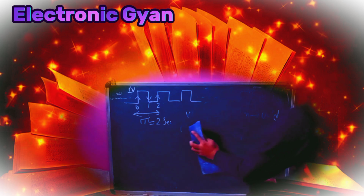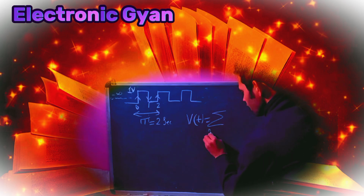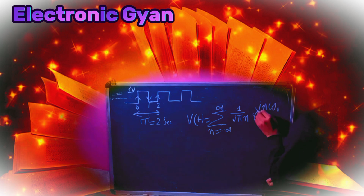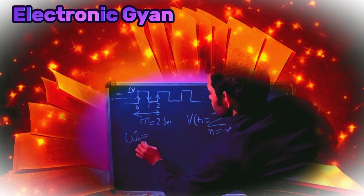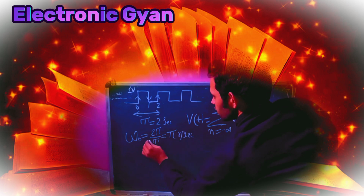Now we are going to find the Fourier series expression for the square wave pulse. That is nothing but v of t equal to summation n equal to minus infinity to plus infinity of Cn, where Cn is 1 by j pi n, e to the power j n omega naught t. Here omega naught is 2 pi by T. T is 2, so it is pi radian per second.